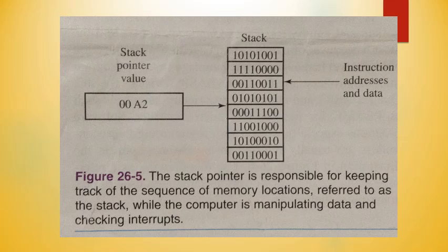For example, a program is written by a user and contains an instruction calling for checking the input value of I/O pin 36. If there is no I/O pin 36, the microcontroller will wait forever for input. It will not process the next command until it receives input from pin 36. Without the watchdog timer, the microcontroller would halt and thus fail to process further instructions. The watchdog timer uses a routine that is based on timing.